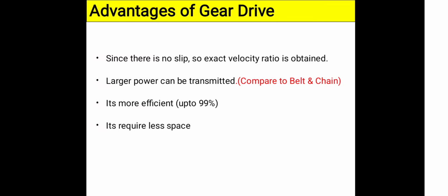Next, in the spur gear the teeth are parallel to the axis of the shaft, so it is called a spur gear. A spur gear will mesh only with another spur gear. The next one is the helical gear. The helical gear has some inclination. The tooth profile is inclined with the axis of the shaft. Here also, gears with the same helix angle and module will be engaged. A spur gear will not be able to mesh with a helical gear.